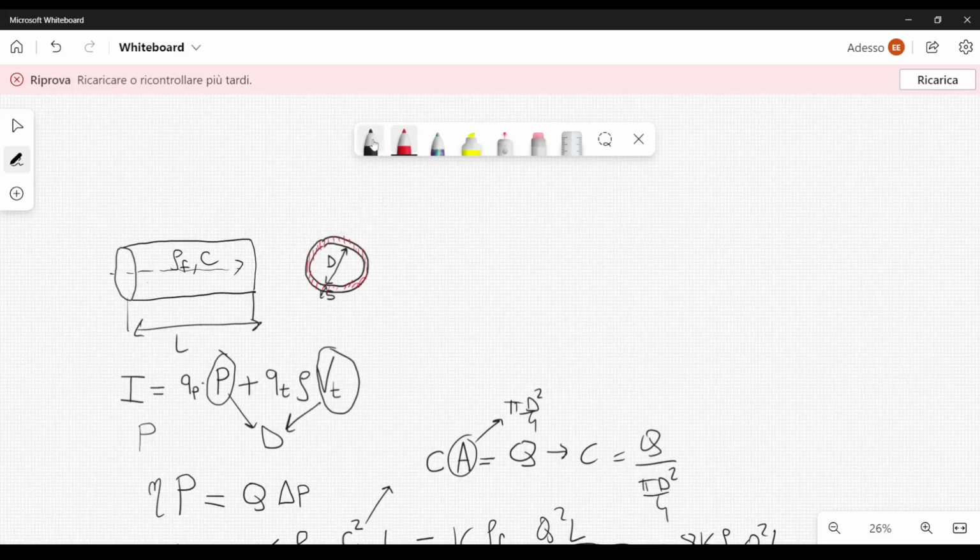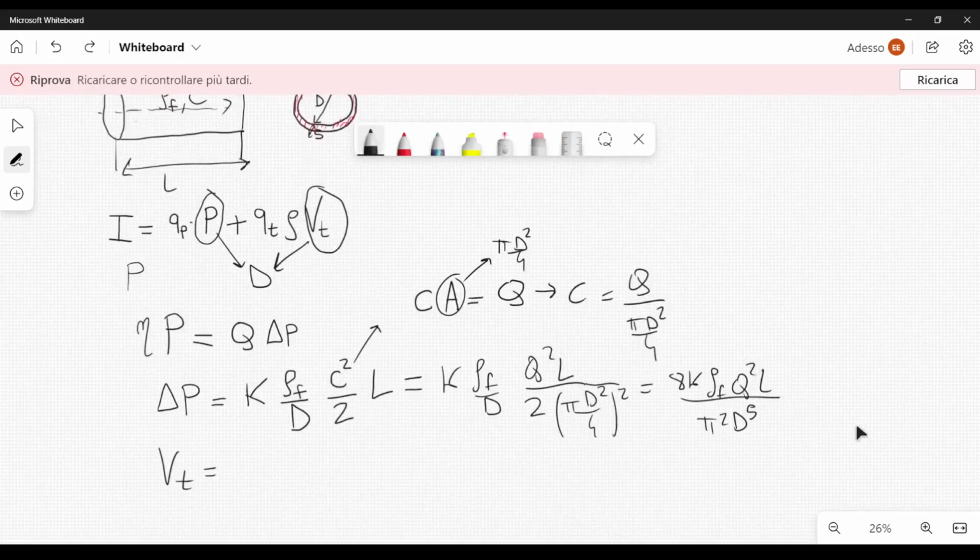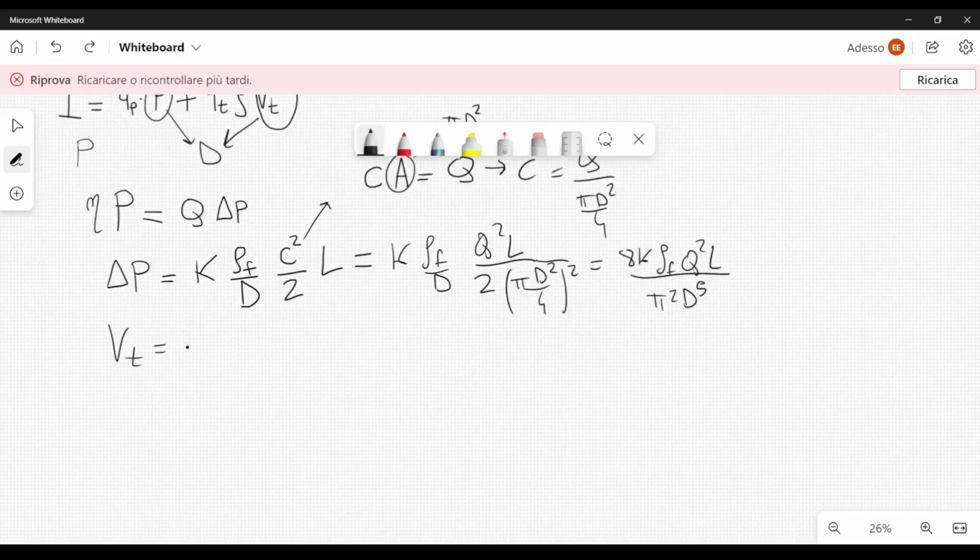in order to find all the volume that we need, because the fluid is passing inside here, but we should not take into account also this volume here, because in here we have the fluid, so the material will be hollow in this part, and the volume can be obtained like this. So we take pi times the external radius squared, so it's 2s plus d squared over 4.